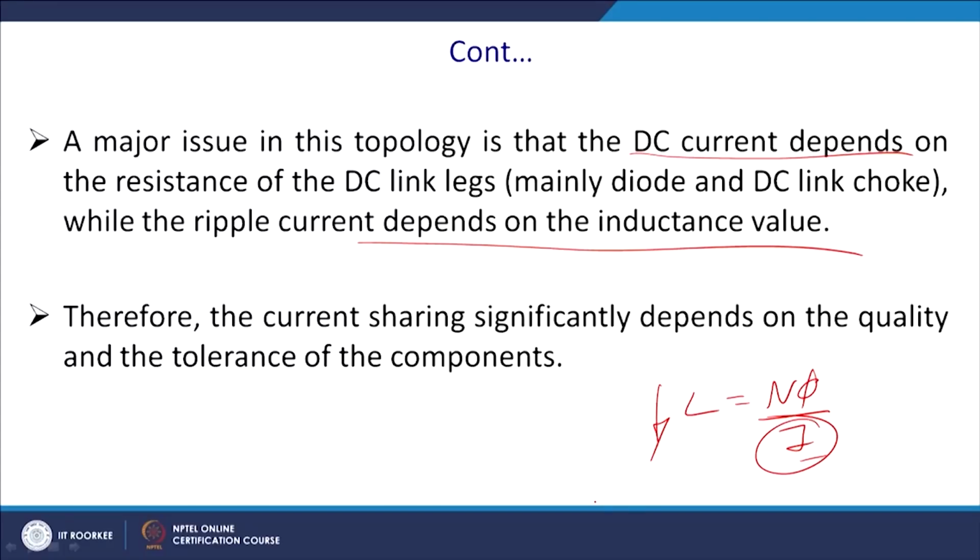So, you have loaded those inductors, then what will happen? If you have loaded that inductor with a better material like Koolmu, it will have different characteristics, and if you load an inductor made of ferrite, you will find a very great roll off, and the value of the inductance will come down drastically from its 100% to maybe 30% value. So, those variations have to be considered in our design.